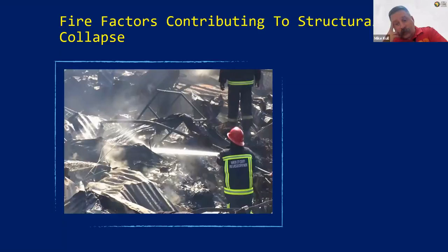A lot of times here in Africa, we see buildings and the building is sort of finished, but the top floor, you can see the rebar sticking out at the top where they've left room to add more floors down the road when money comes available or we need more space, right? But was the bottom half of that building built to hold those extra additions, those extra floors? So maybe the addition of those extra floors may be a contributor to a collapse. Maybe they've overloaded the building.